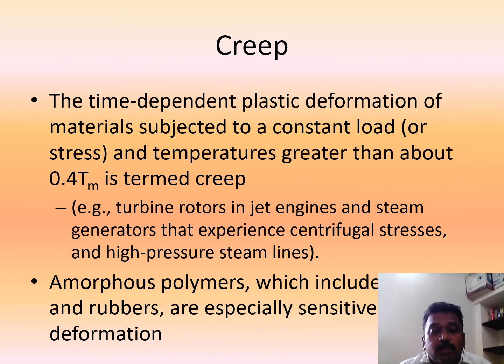And then next comes creep. Creep is the time-dependent plastic deformation of a material subject to a constant load or stress at temperatures greater than about 0.4 of the melting point of that material. So that is time-dependent plastic deformation. You are applying a constant load, and the temperature is more than 0.4 of the melting point of the respective material.